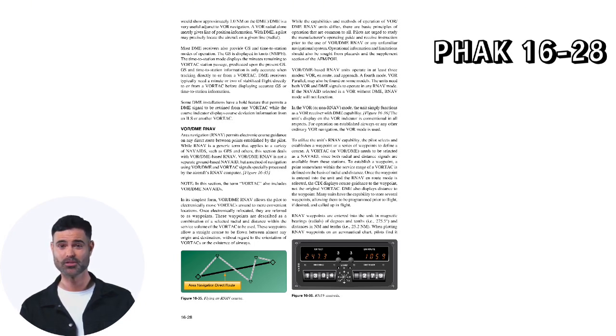These waypoints are described as a combination of a selected radial and distance within the service volume of the VORTAC to be used. These waypoints allow a straight course to be flown between almost any origin and destination, without regard to the orientation of VORs or the existence of airways.